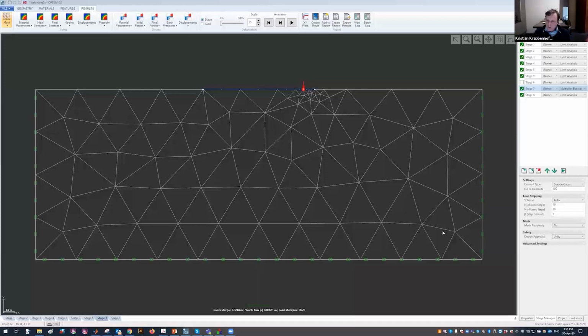Yeah, inclined loading is of course possible to take into account, but are you talking about the case where the foundation is embedded? Yes, the foundation is embedded, and just imagine the problem that we have is for a pipeline, actually. Sure. Then you're in earth pressure theory, not bearing capacity theory, right? That's how it would usually be thought of.